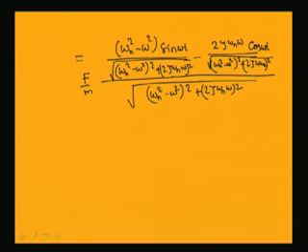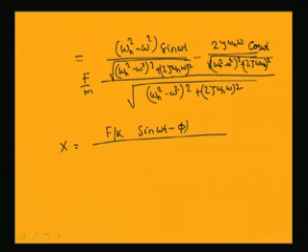So, from this one can observe that this can be written in terms of sin A into cos B minus cos A into sin B form. So, this thing can be taken as cos phi and this thing as sin phi. So, sin omega t into cos phi minus cos omega t into sin phi form, this can be written. So, this x can be finally written as f by k into sin omega t minus phi by root over